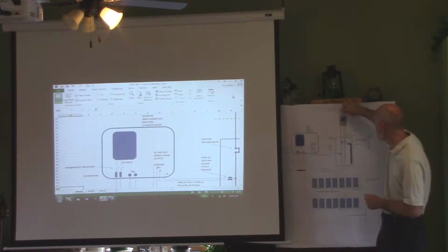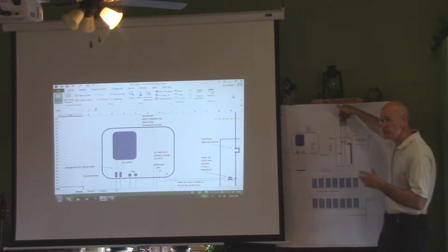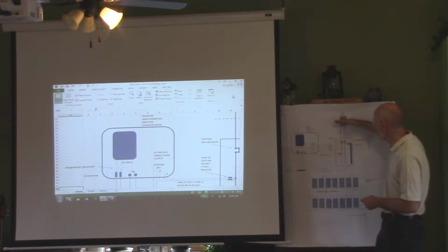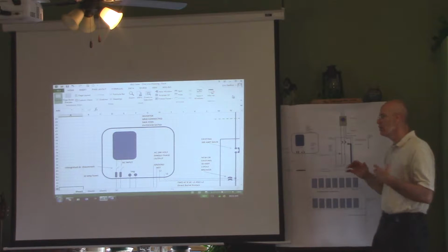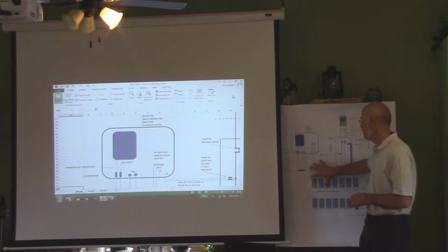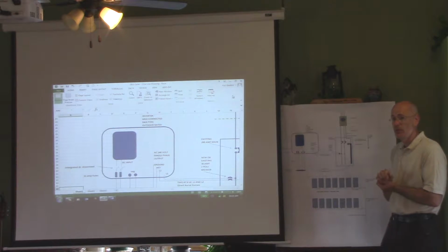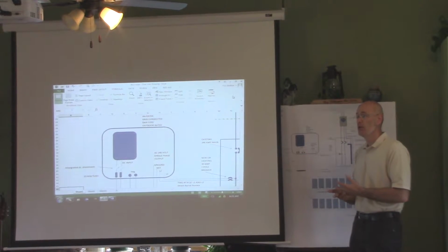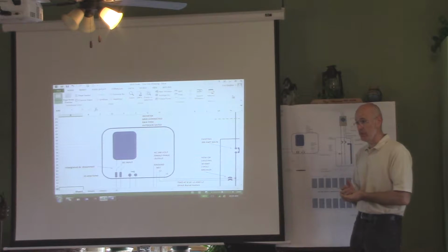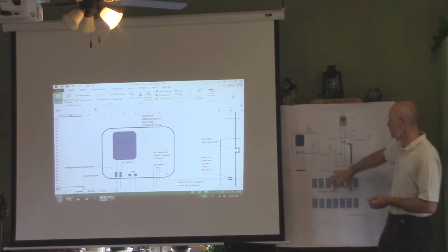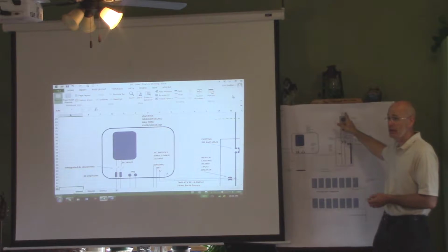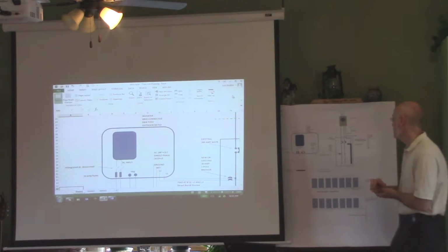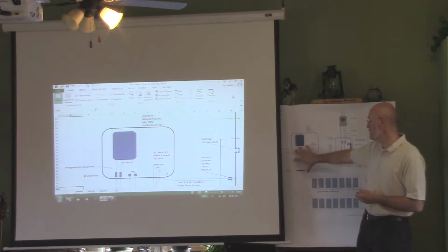Here's the utility up here, this is your utility meter. The wire's coming into the meter on your house, you're all familiar with the meter on your house. They own the meter, you own the socket, and that's the line of demarcation right there. Okay? They own this, you own that. You're not going to connect anything that produces power to their wires without their permission. And this is a big deal. A big deal for me in my career, because I was building big power plants for hospitals and factories, and they didn't like it because, see, they make their money selling you power. If you make your own power, you're not buying theirs. And they don't like that because they want you to buy their power, supply and demand. So you've got to get permission from them to hook up this.